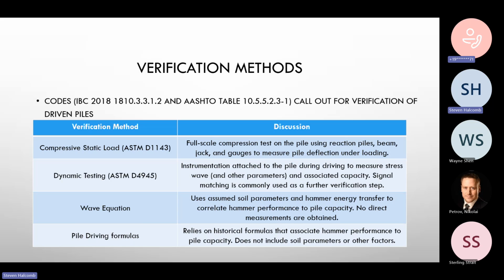And I guess that's kind of where we like to be, when you factor up your loads beyond what you're actually going to use, and you factor down your resistance. You live in this camp where you've designed it way over what it should really see, and you really shouldn't see a lot of movement. But the reality is, when you load a pile, no matter what, it's going to move down, either strain with the steel, or the soil will strain.